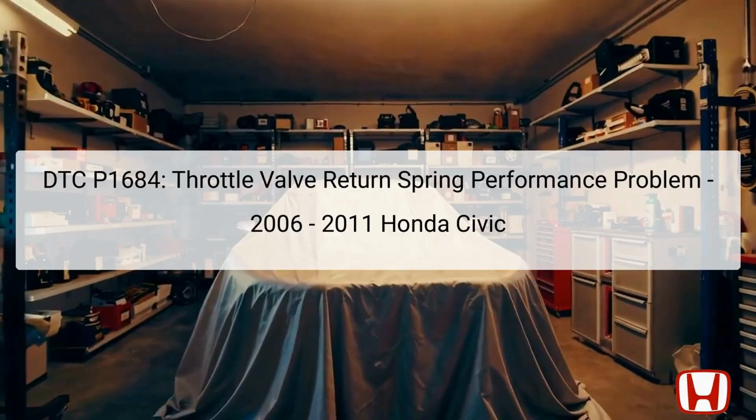The DTC P1684 indicates a performance problem specifically related to the throttle valve return spring in Honda Civics from the years 2006 to 2011. This error code is significant as it can affect the engine's ability to idle correctly, directly impacting overall vehicle performance and safety.